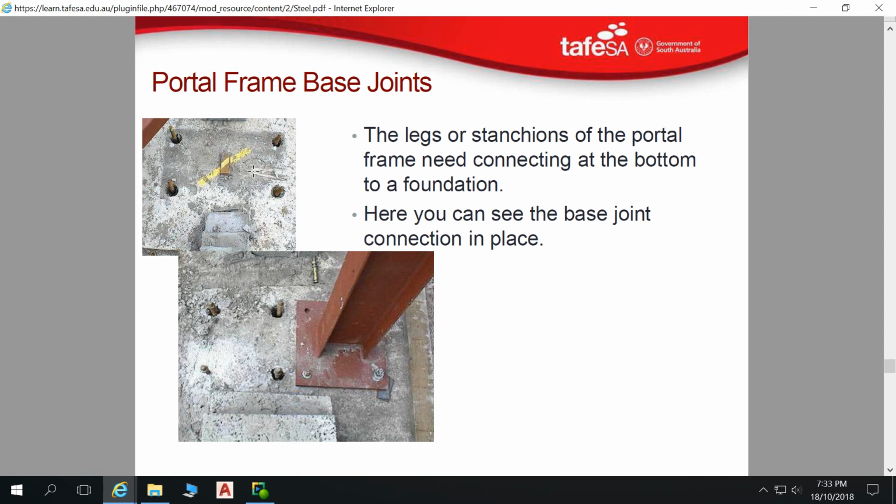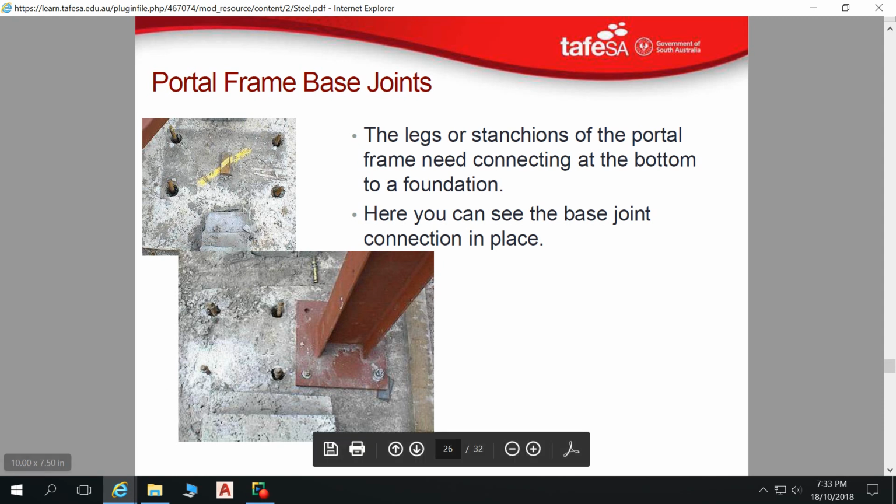these large portal frames, because they're holding a whole roof, and as you get high winds that pour over that roof, it's putting racking forces on there, which is trying to tip the portal frames over. But you also get that uplift as the building works like an airplane wing. With the wind, it's trying to suck it up. And because your portal frames might be like 12 meters apart or something, you've got some massive spacings, they end up having huge uplift.